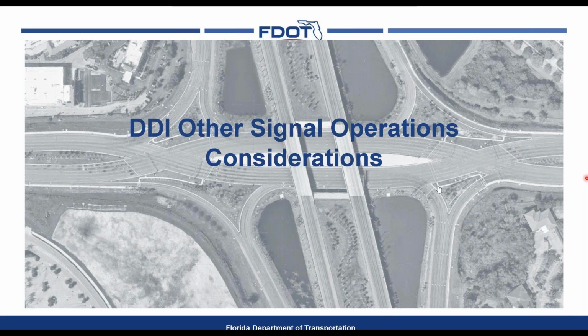Yeah. So we have looked at that before, whether you're trying to get the off-ramp through to a two-way street on the other side or a frontage road, and you do have a high through volume. It is possible to do it. However, it does put you into a three-phase signal for sure, because now you can do through movements one way, through movements the other way, and then the off-ramp through, which is going to reduce your capacity at the interchange. And another thing, it does get difficult to do, as we'll talk about later.